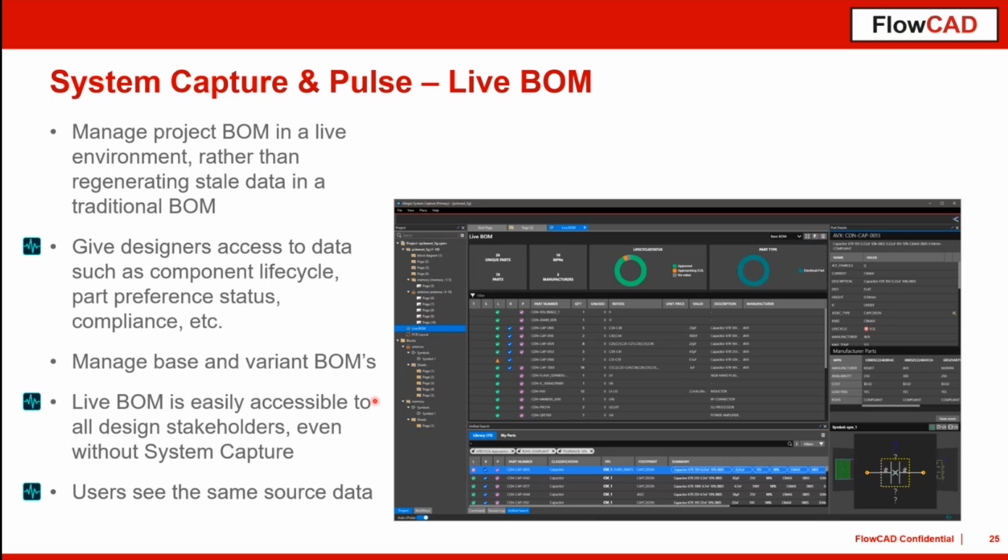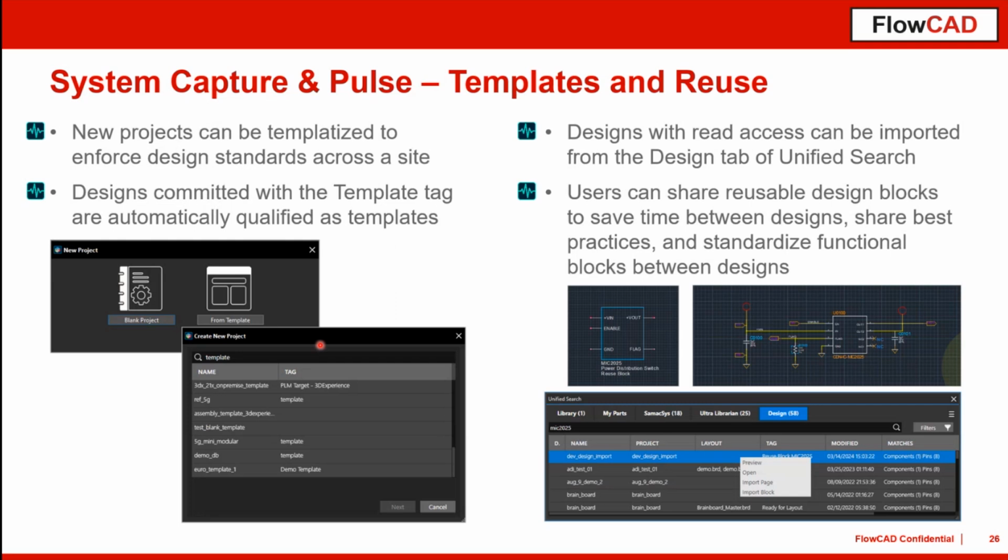And therefore you always have the live BOM, always up to date BOM somehow. So this is also a good thing. Capture or OrCAD Capture users already know about this. This live BOM functionality has also been built in in the meantime, but for HDL users, it's a pretty new thing.